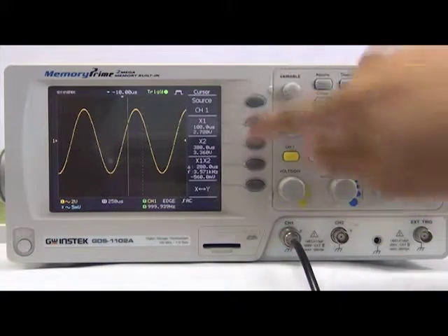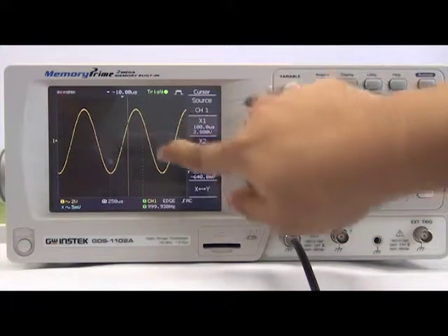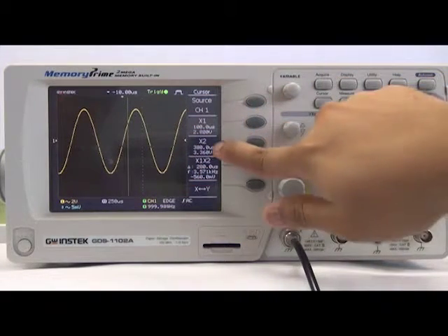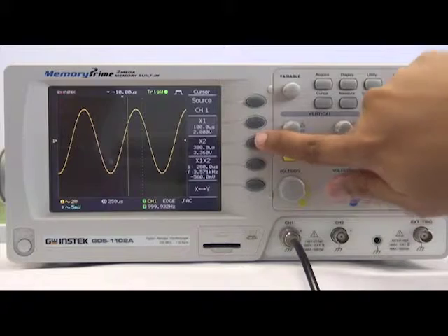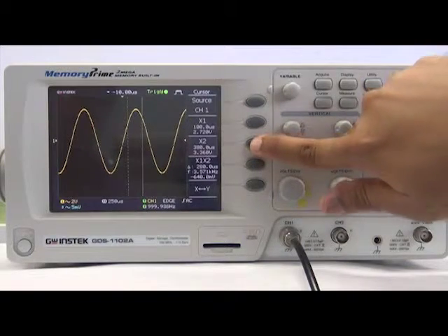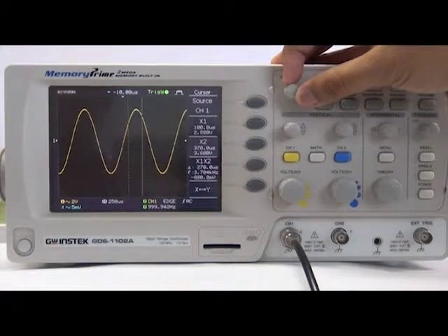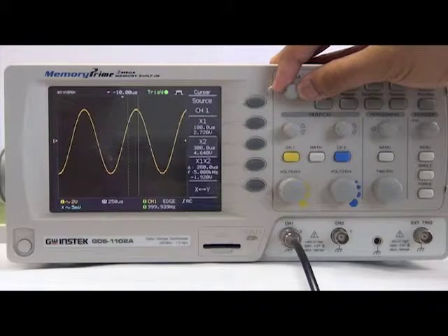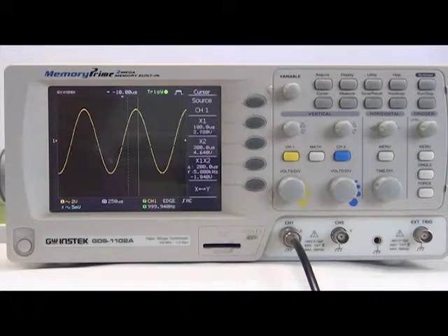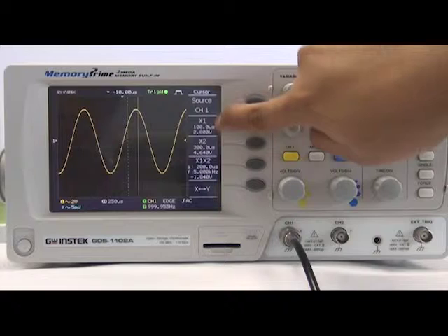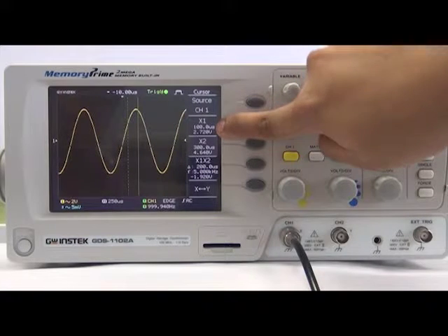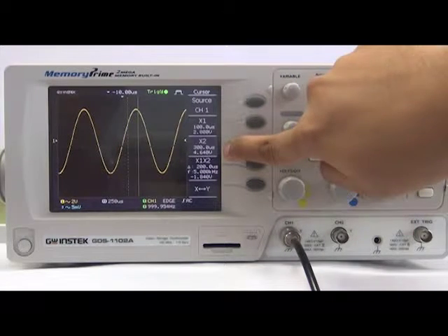Now we have to change the X2, which is currently the dotted line, to 300 microseconds. Press the button belonging to X2 and turn the variable to 300 microseconds. When you're done, you will now notice that the voltage belonging to X1 is 2.8 volts and X2 around 4.6 volts.